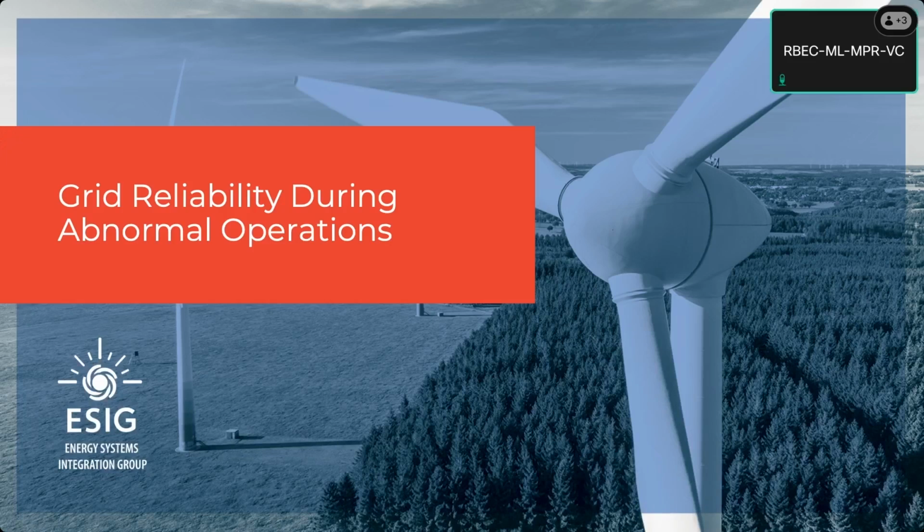All of the transmission planners know about this, and those studies are usually done routinely, or when something changes. So if you want to add a new IBR plant, or a new STATCOM, or you want to change your transmission system somehow, that will trigger a study process, and that will bring all of the new stuff into the old stuff, ideally. Now, those processes can get behind, they can be too slow, they can be inadequate in a lot of ways, but it's something that we know. If you change something, you have to study it, right?